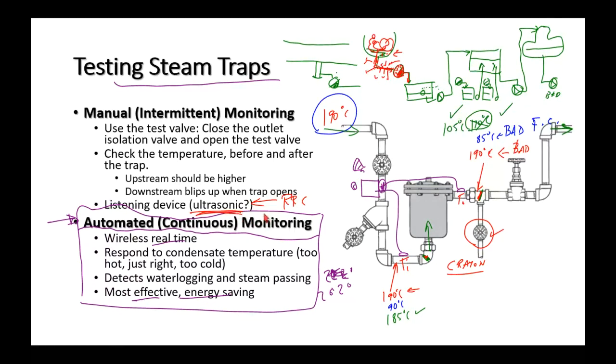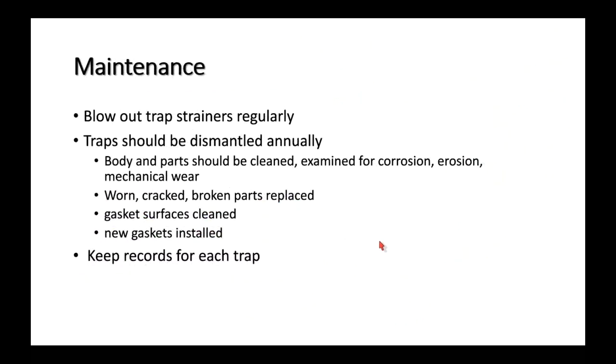I think you'd have to take some kind of a course in learning how to interpret the beeps and sounds that this thing makes as you're listening to the trap. But the whole idea is, if you know that a bucket comes up and then goes down, or a disc opens and shuts, or an F&T trap makes a hissing sound, then hopefully you'll be able to differentiate between all of these different sounds and say, oh yeah, the trap works, or no, it doesn't. Frankly, I don't think it's very effective. I think temperatures are far more effective.